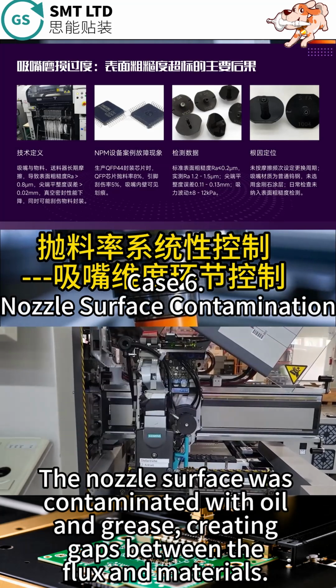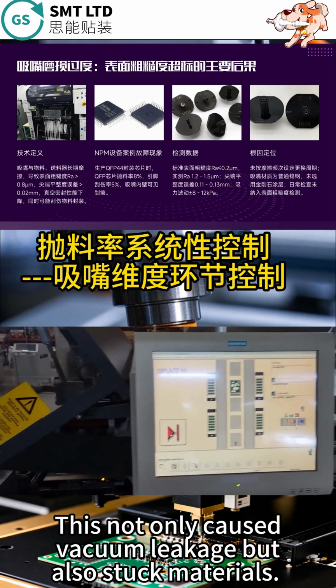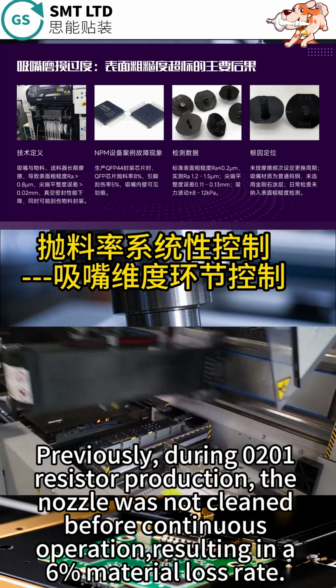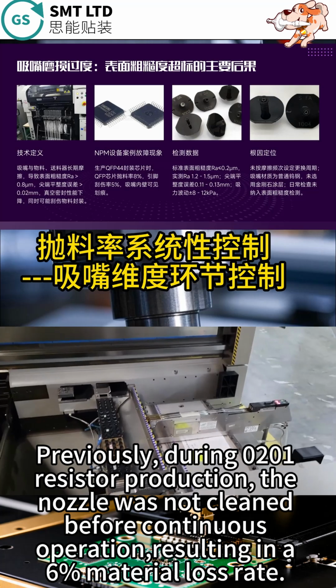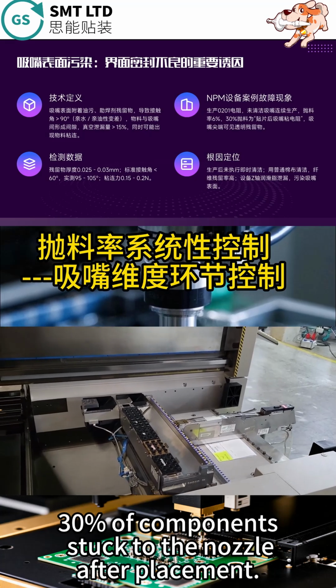The nozzle surface was contaminated with oil and grease, creating gaps between the flux and materials. This not only caused vacuum leakage, but also stuck materials. Previously, during 0201 resistor production, the nozzle was not cleaned before continuous operation, resulting in a 6% material loss rate. 30% of components stuck to the nozzle after placement.